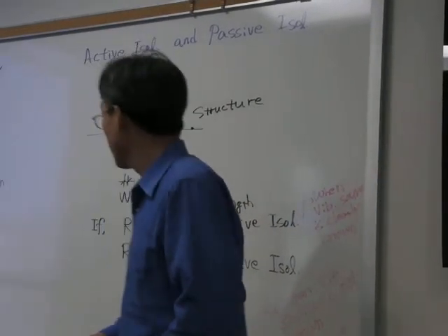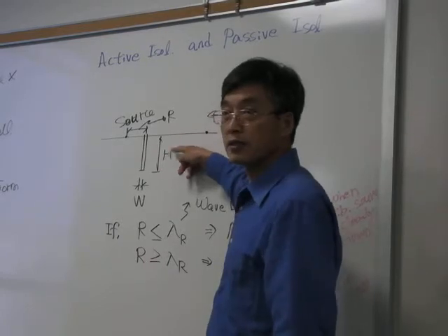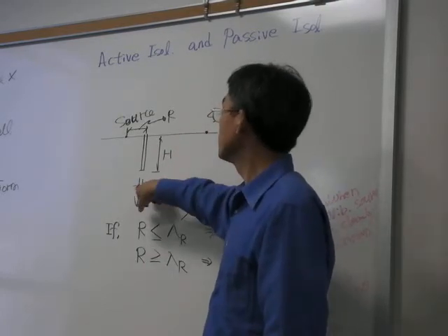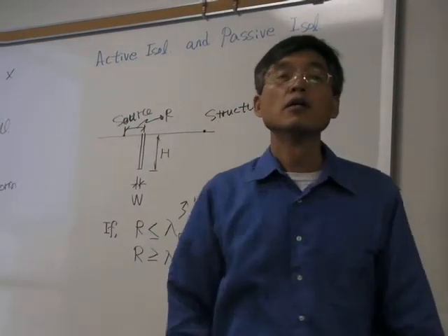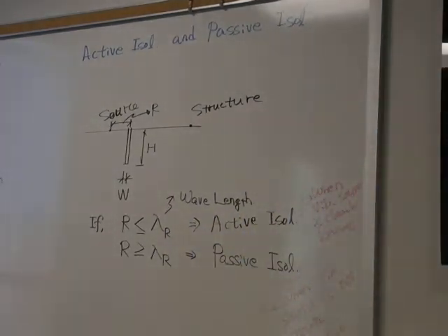Then we know that the depth of the trench, the width of the trench, and this distance will all affect the performance of our trenches, in addition to the soil properties, right? So we will think about how we can actually design vibration isolation.